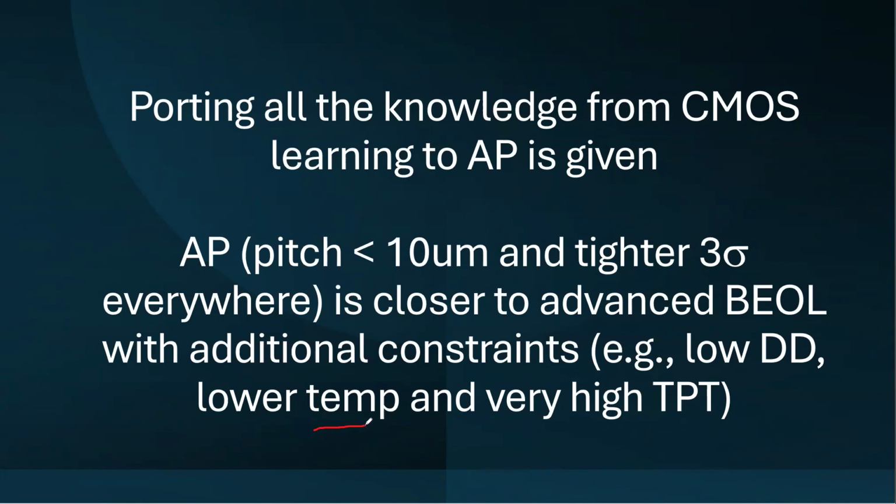And usually temperature is low, because your pre-manufactured good dies cannot withstand high temperature. Anything above about 480 or 500, you're doomed, because the die on top will be dead.